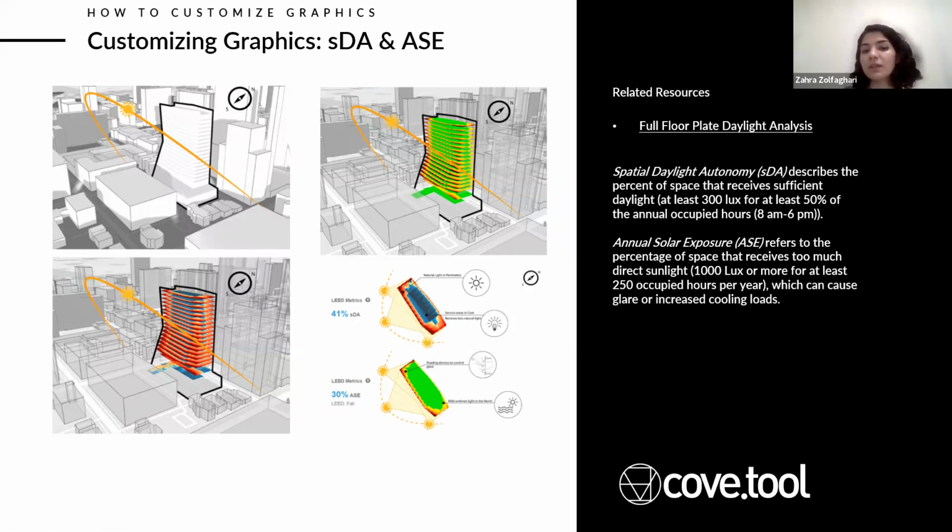These images clearly show that the glare situation in the south facade of the tower can be enhanced by using effective horizontal shading devices. Also, the heat map colors on the plans indicate the depths of daylight penetration. Knowing this information helps design teams decide about the interior layouts, the location of interior walls, furniture, and also the visible transmittance of the glass material they want to use based on the glare and the SDA, the daylight that the plan receives.